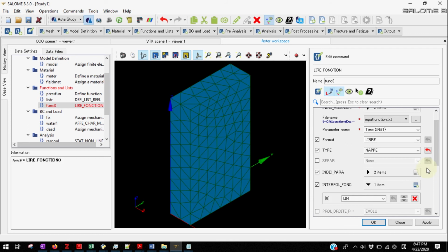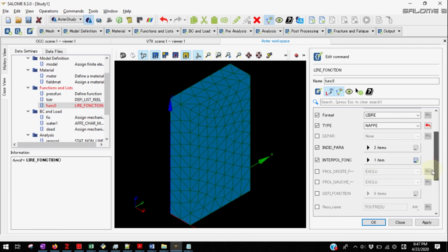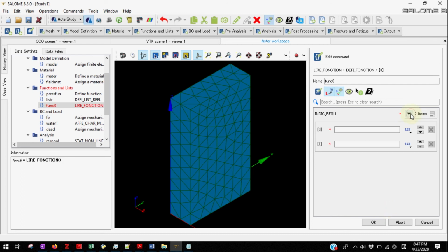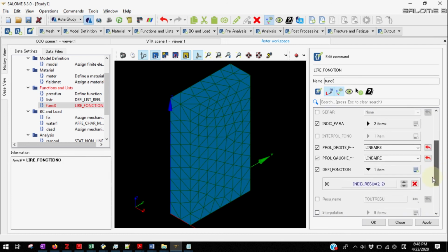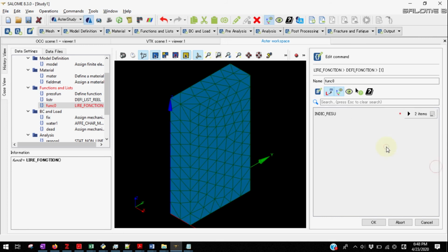This is not an interpolate function. What I want to do is first define how the interpolation will be done. It will be linear. And for the ordinate function part, we'll write for each time step the required value. The first one is second block, second column. So 2 comma 2. Similarly for time step of 1 and so on, we'll define the varying Z function.